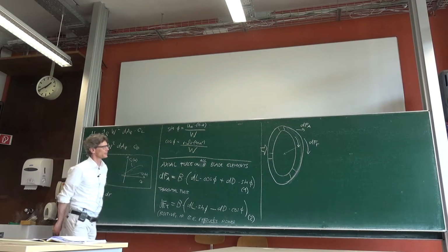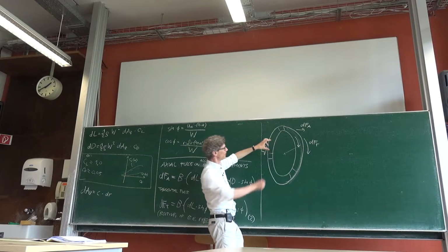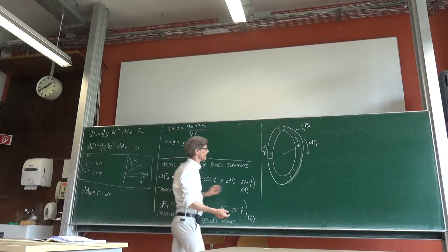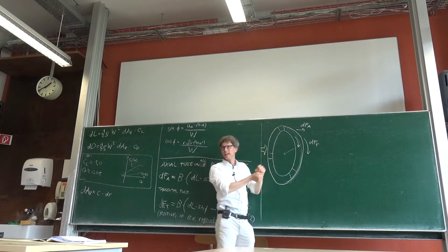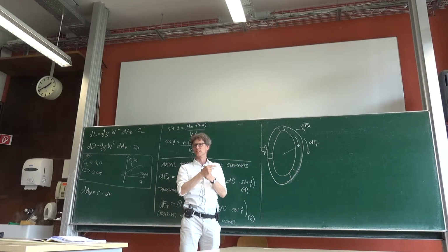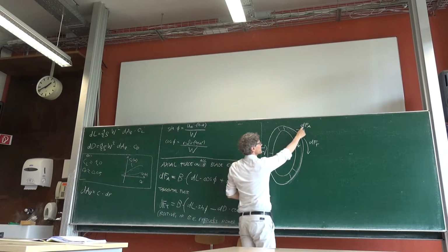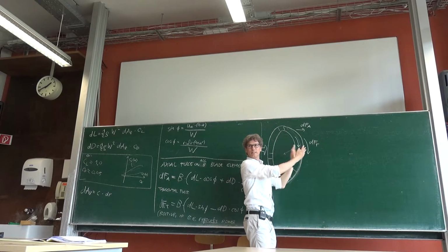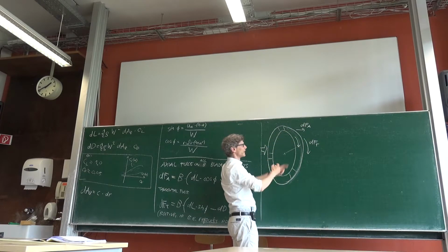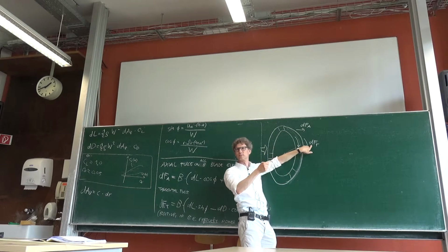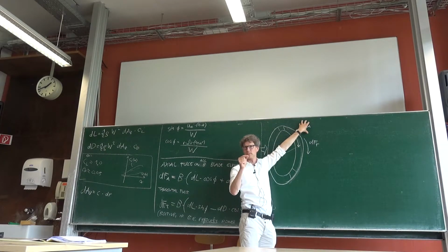So now we know that this whole annulus has air flowing through it. And this air, on the B blades, B the number of blades, exerts a certain force in this direction and another force in this tangential direction. Because of conservation of momentum, the airflow must also get a change. It must slow down due to this force. That's the actual induction that we had before. And it must also get this extra rotary motion in the other direction because it has this tangential force to produce. Let's start with the slightly easier one, which is the axial induction.